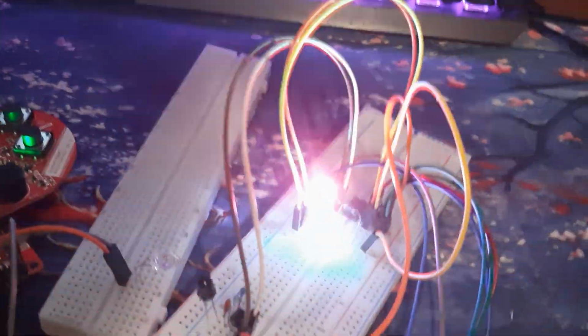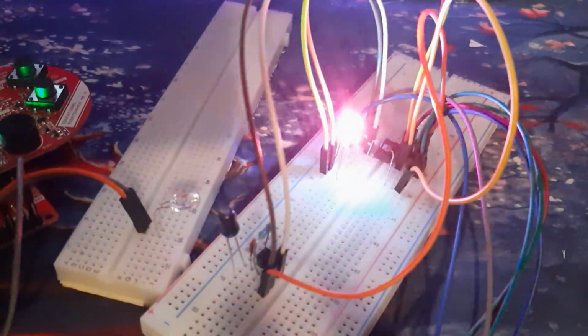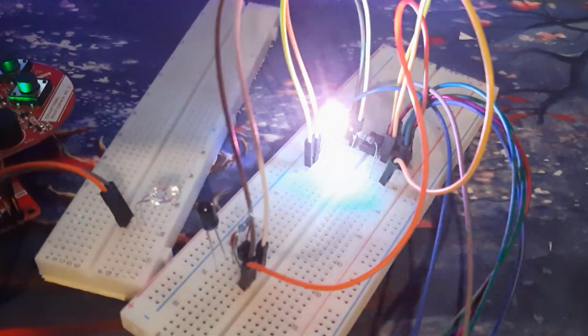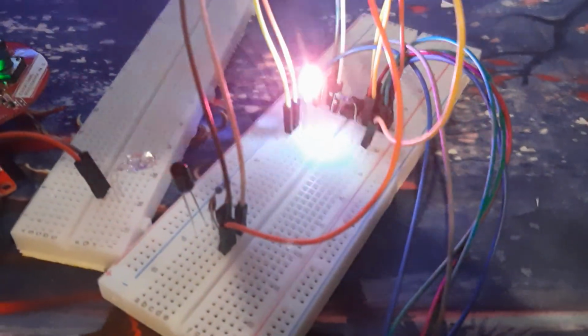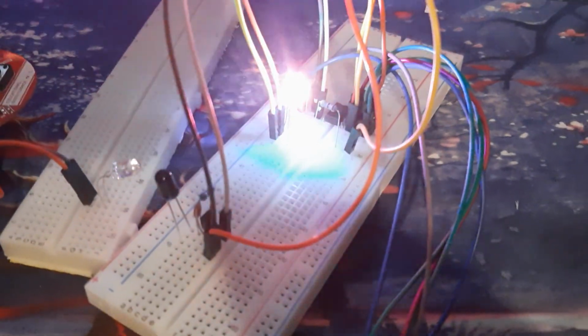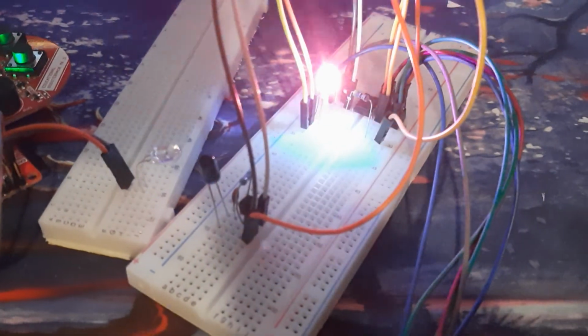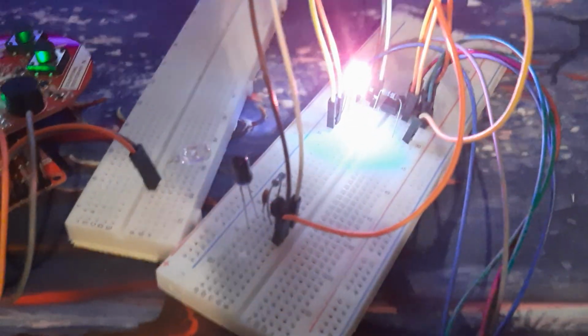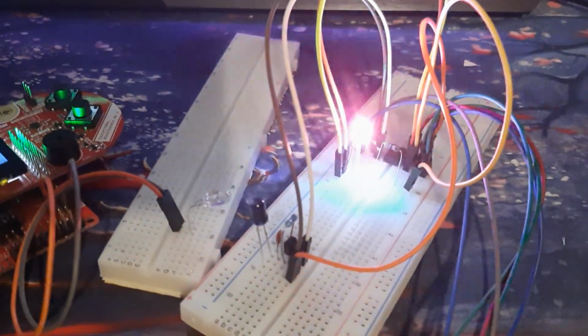But let's get into the transmission. In order to transmit the bits, I was planning to use the standard IEEE Manchester code. I couldn't use the standard Manchester code since I don't have a timer.